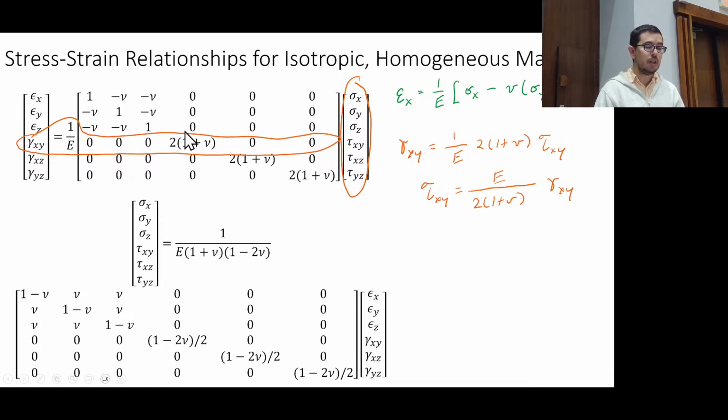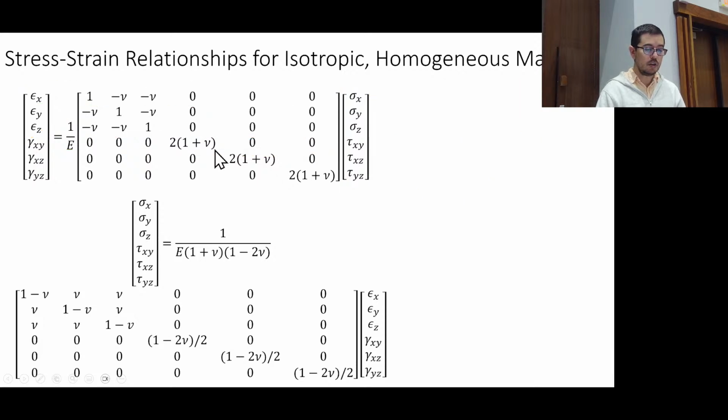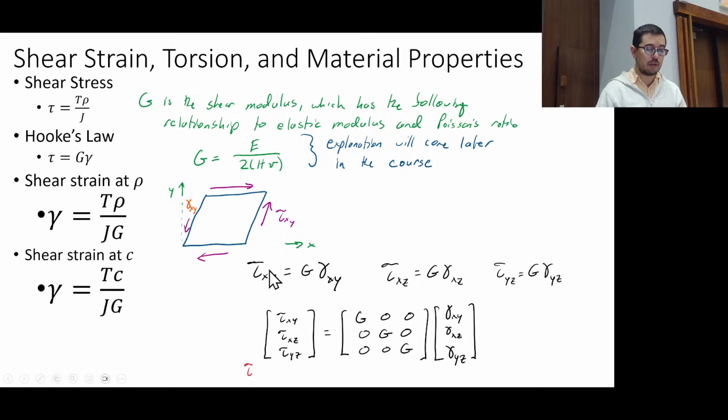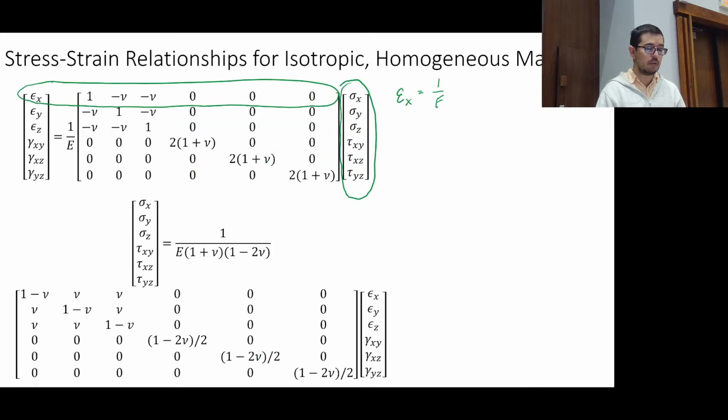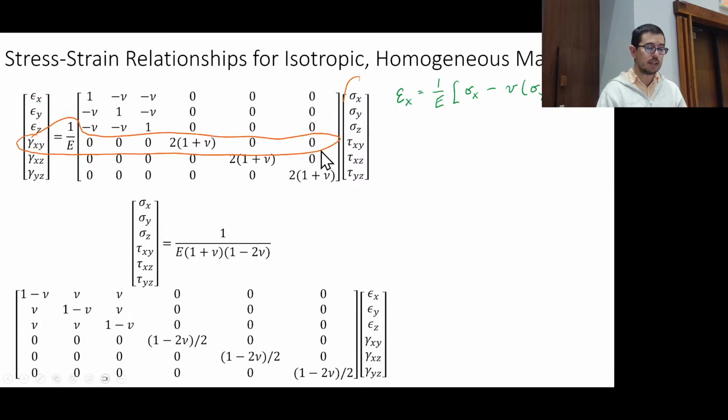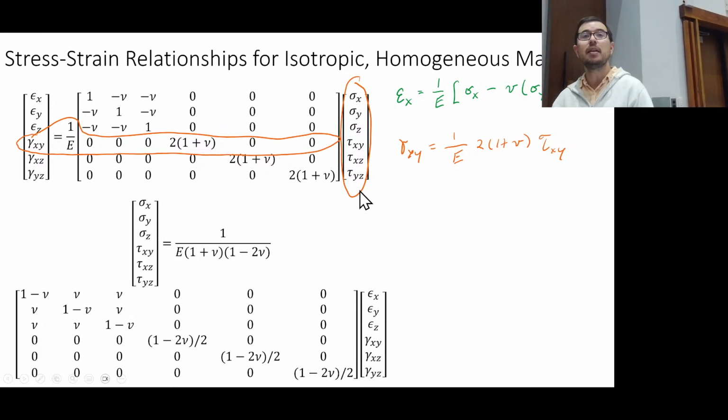We saw that here, and I maybe was leading up incorrectly to say that if you have normal stresses in the other two directions, it affects what's happening with epsilon. Well, here it doesn't. Gamma xy is only going to be dependent on the tau xy. It's not dependent on the tau xz and the tau yz. Any questions on this?